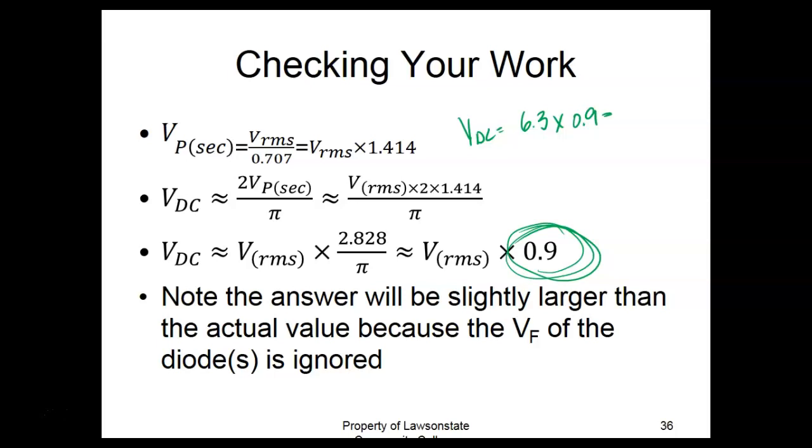So 90%. So 0.567. 5.6. Yeah, ain't that neat? A while ago when we took out the diode drop and went through the math, we came up with 5.4 volts. Ignoring the diode drop and just taking the input voltage and multiplying it by 0.9, you'll come up close enough. So odds are you could answer just about any question on the test. Unless we had 5.4 and 5.6 on the test, then 5.6 would be wrong.